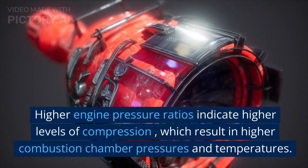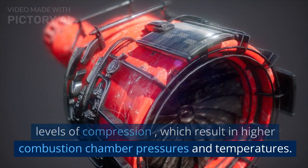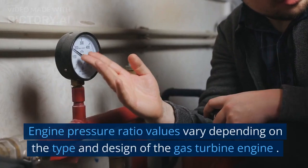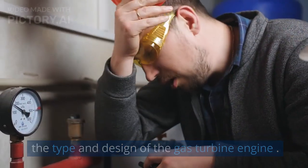Higher engine pressure ratios indicate higher levels of compression, which result in higher combustion chamber pressures and temperatures. This leads to improved engine efficiency and higher thrust output. Engine pressure ratio values vary depending on the type and design of the gas turbine engine.